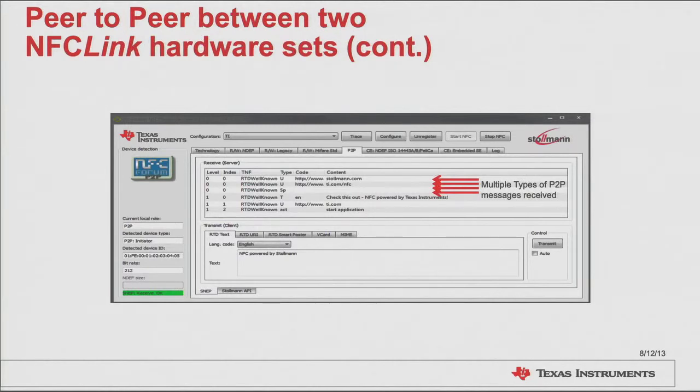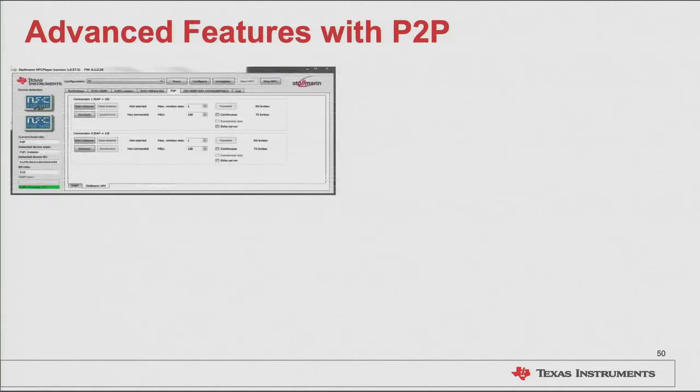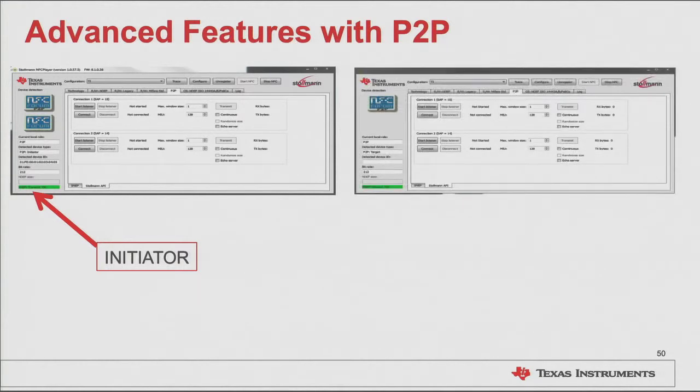It is important to realize here that once the connection and symmetry is established, the device on either side can send something to the other device without changing any settings. The NFC Stack GUI has an advanced peer-to-peer feature where the user can establish a 2-channel bidirectional communication link between 2 kits. This will be useful for firmware updates or large data transfer when the user can set a device down for at least a few seconds.